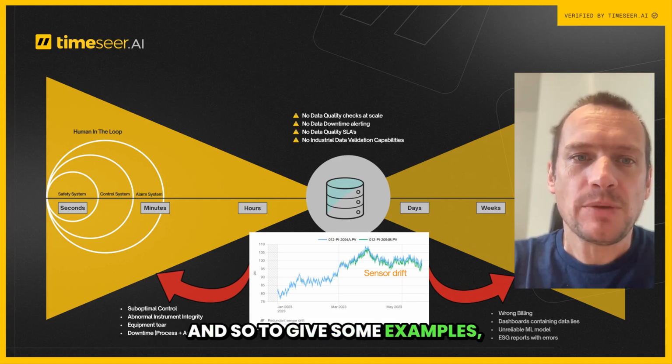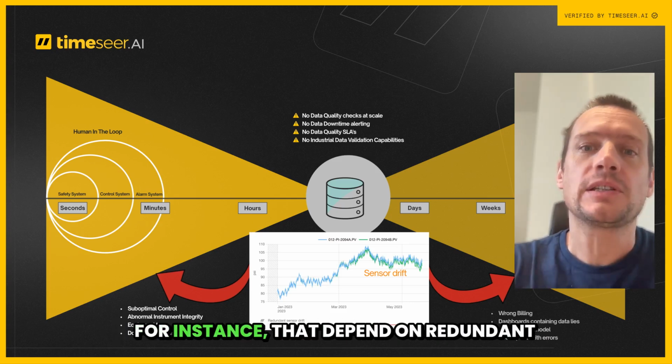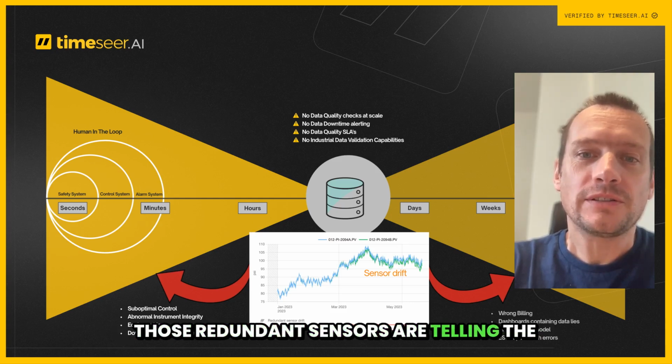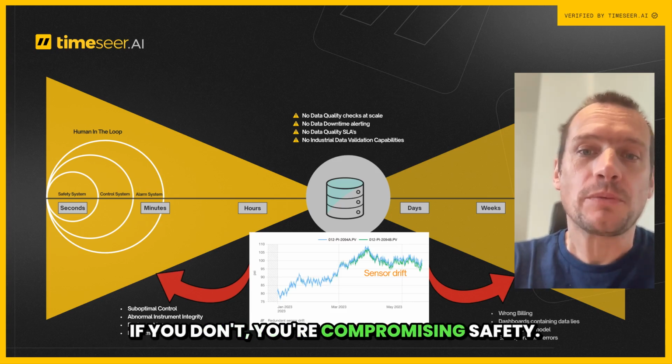And so to give some examples, if you think about operations itself, it starts with safety. If you have safety instrumentation systems, for instance, that depend on redundant sensors, then you'd better monitor whether those redundant sensors are telling the same story, yes or no, because if one of them is drifting, you need to repair, you need to take action. If you don't, you're compromising safety.